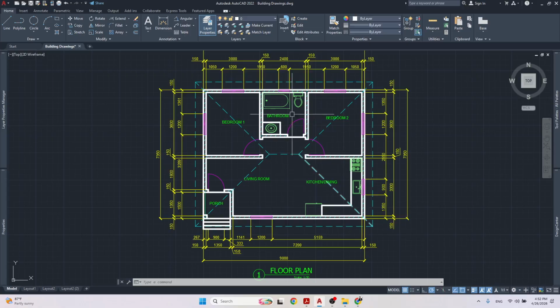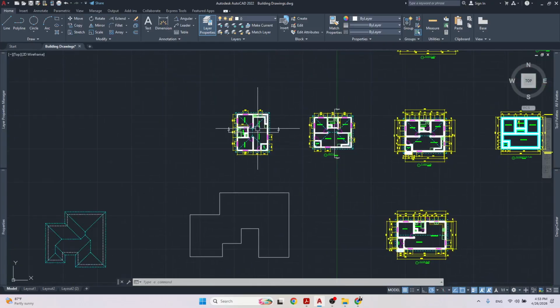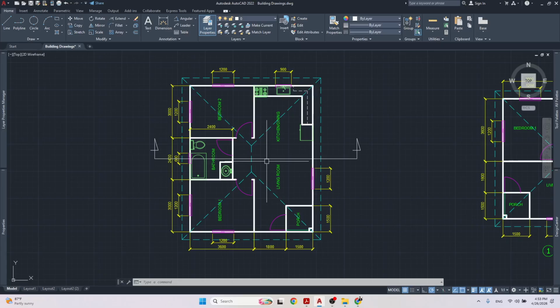In real life, what I typically do, because the floor plan would be one of my first drawings and then everything else is built after that, I would pull projection lines down. From the projection lines I would get my wall thickness, the location for the windows and the doors and everything like that, and then I would just fill them in where they lie. I'll probably do another video on doing a proper section drawing, but for the sake of this video and preparation for CSEC exams, I'm going to do it with just the line sketch.